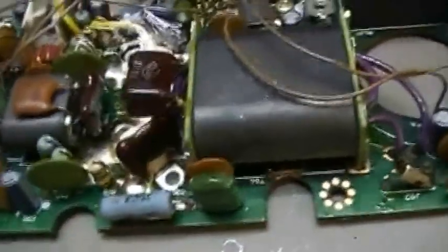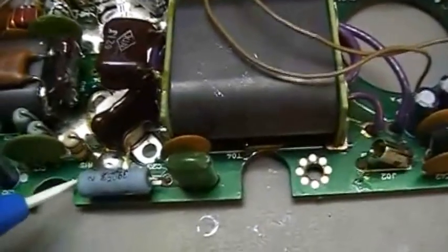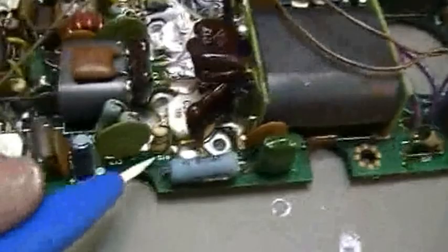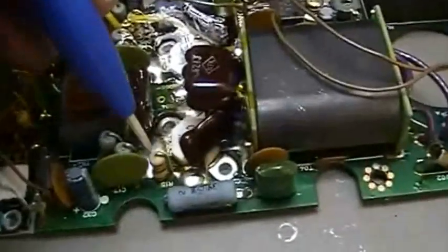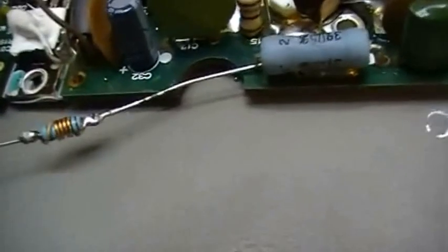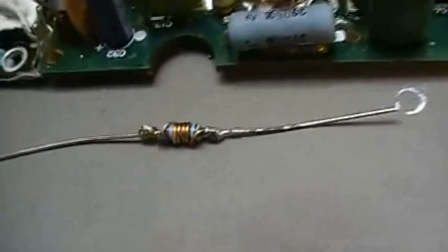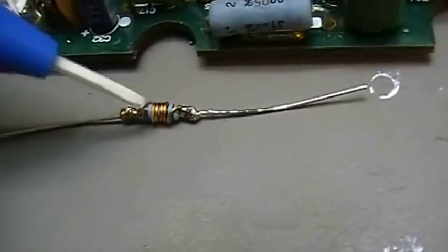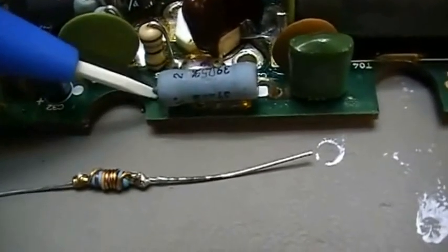and we can check our resistors, which are here and here, and this side of the resistor is connected to the base of the final transistor, and we are going to take one side out of the PCB right now, and then we put our little coil in between, and then we will see if this can stop the self oscillation or not.